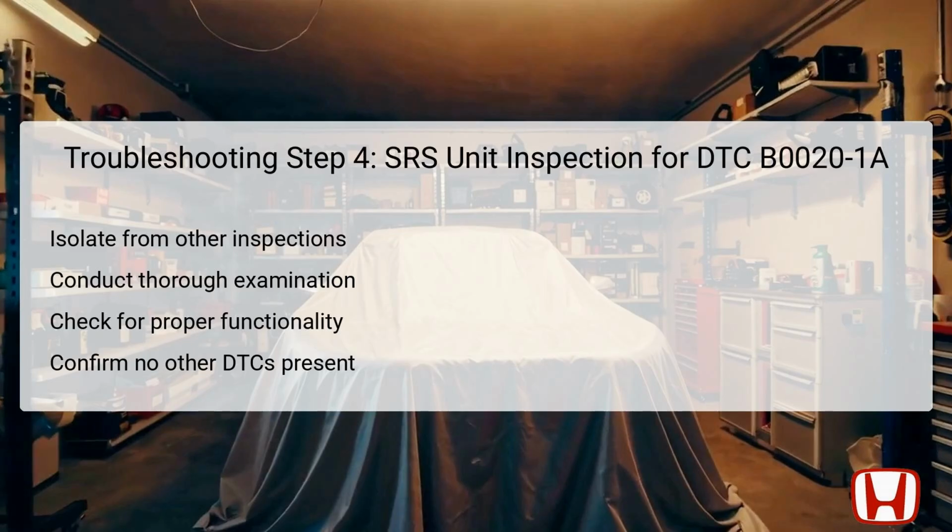Additionally, ensure that there are no other diagnostic trouble codes present, as the presence of additional codes could indicate broader issues within the SRS system. If the SRS unit is found defective, replacement may be required to restore airbag functionality and, by extension, vehicle safety.